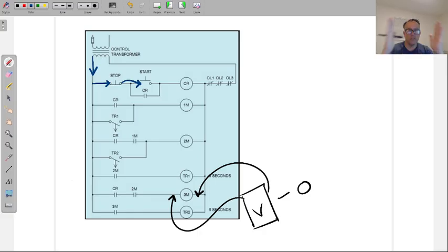where something has happened. Now, this is not a conversation in control circuits, so I don't want to get into the things about the coils and the contacts not closing or whatever the case may be. But this is the point-to-point approach. Now you might be saying, well, hey, this is going to take a while. Yes, but it was going to take a while anyway. I just now am going through the process confident that voltage is in the circuit. Whereas if you were working your way backwards, you still don't even know if voltage is here.